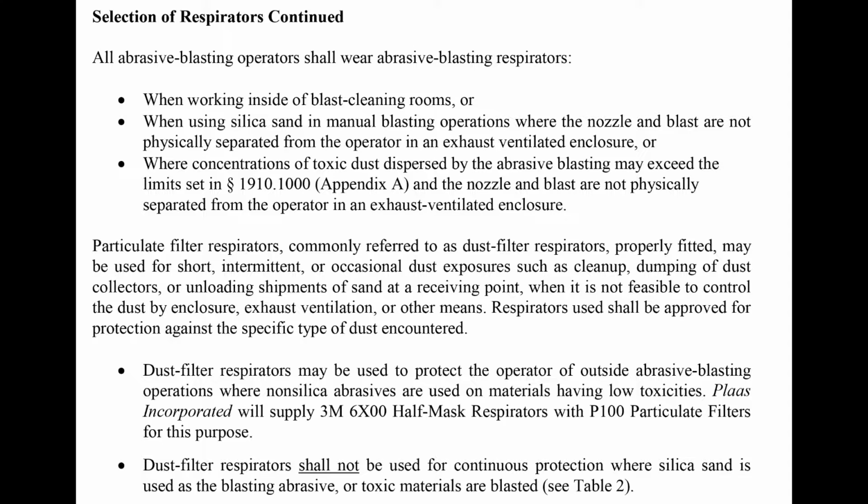Selection of respirators, continued. All abrasive blasting operators shall wear abrasive blasting respirators when working inside of blast cleaning rooms or when using silica sand in manual blasting operations where the nozzle and blast are not physically separated from the operator in an exhaust ventilated enclosure, or where concentrations of toxic dust dispersed by the abrasive blasting may exceed the limits set in 1910.1000 Appendix A, and the nozzle and blast are not physically separated from the operator in an exhaust ventilated enclosure.